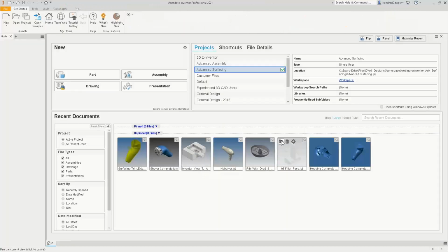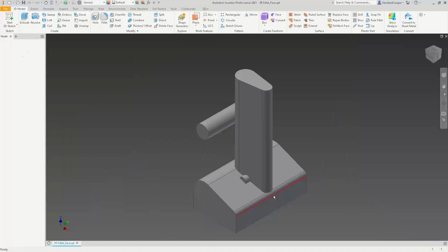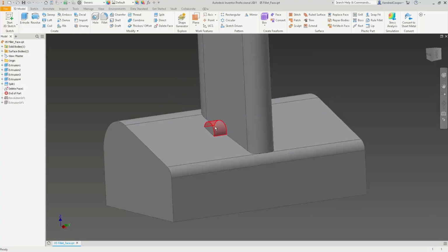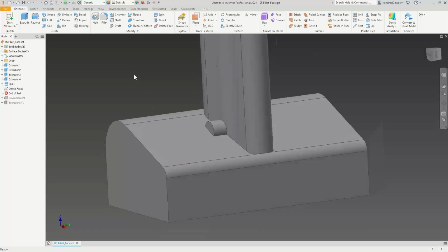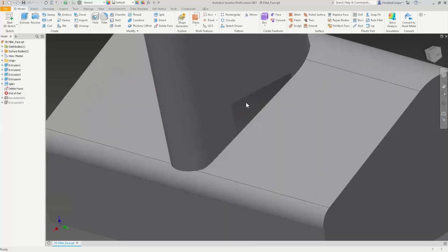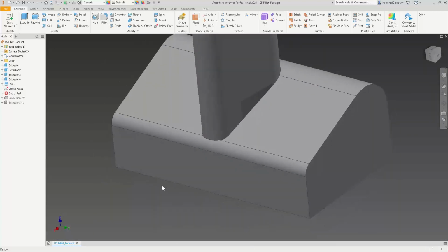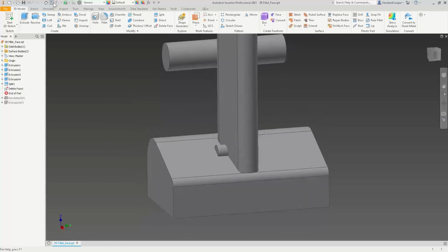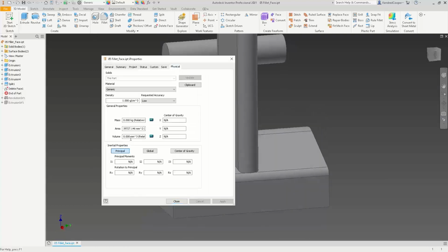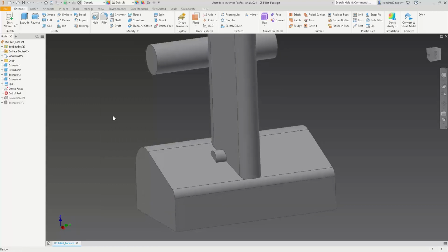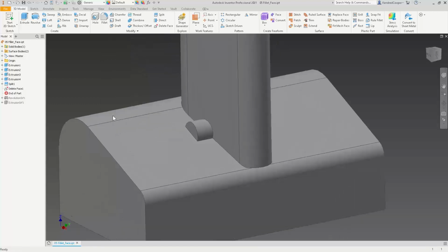So if we take a model like this guy right here, got a couple of things going on. We've got a little piece of feature material coming out here. On the back side, we have an open gap inside the model. This is an actual cutout, and you're looking down into the inside of the model. It's a surface model. There is no mass or volume associated with this. Everything zeroes out. Surfaces can help us clean this up.